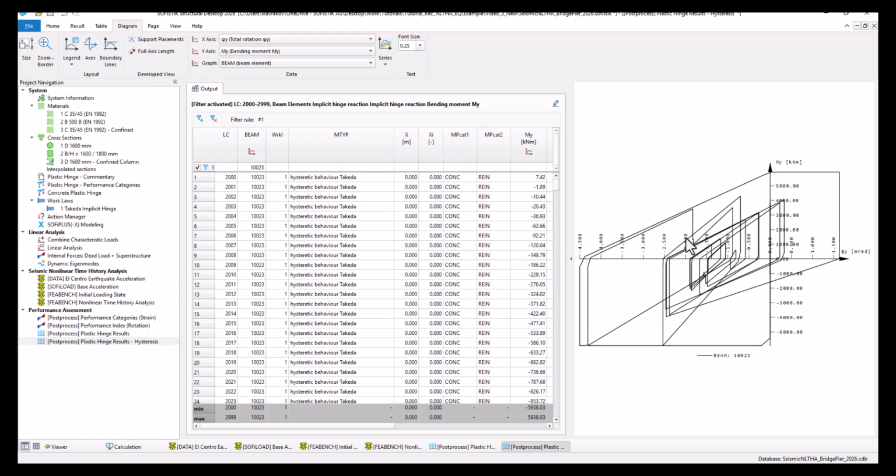We can observe the plastic strain energy dissipation by examining the shape of the hysteresis. The rotation remains very small until the yielding moment is reached, just under 6,000 kN, after which we observe a plateau as the backbone of the plastic hinge, which behaves perfectly plastic. The cyclic behavior in this range follows the modified Takeda model rules discussed earlier in this tutorial.